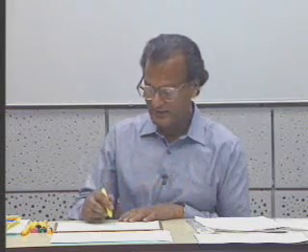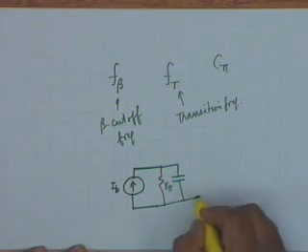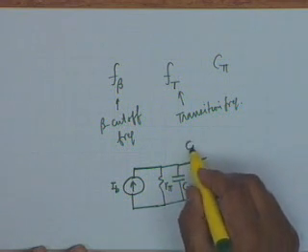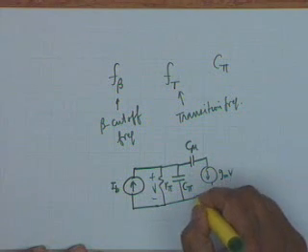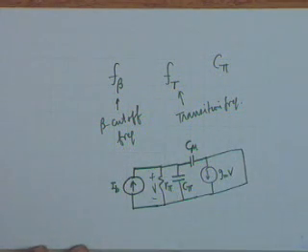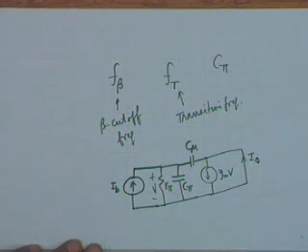Well, in terms of the equivalent circuit, you see in the base you have R pi, C pi, then you have C mu, then you have GMV, this is V, and as I said, you short circuit the collector. Then this current would be I sub C, the output current, the collector current. And the ratio of I sub C to I sub B would be the current gain or current amplification factor, and to indicate that this is done under short circuit conditions, we say this is the short circuit current amplification factor.